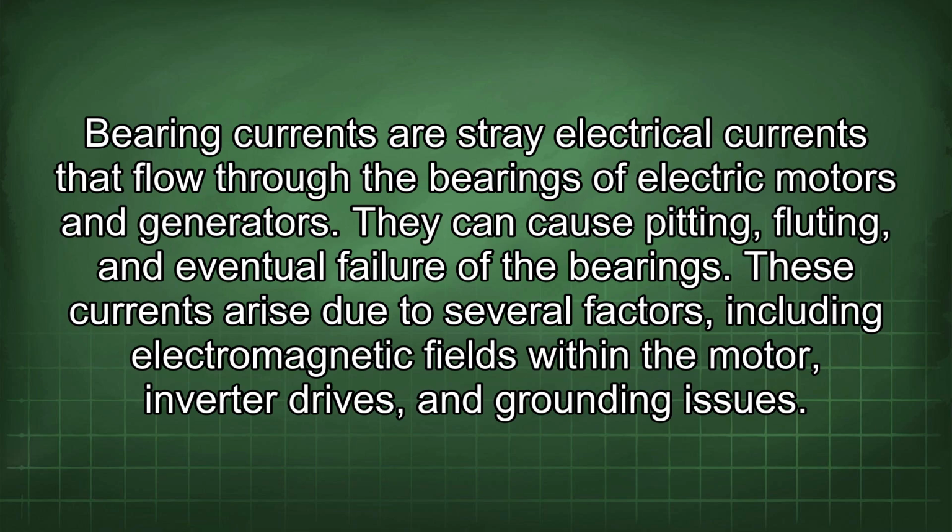Bearing currents are stray electrical currents that flow through the bearings of electric motors and generators. They can cause pitting, fluting, and eventual failure of the bearings. These currents arise due to several factors, including electromagnetic fields within the motor, inverter drives, and grounding issues.